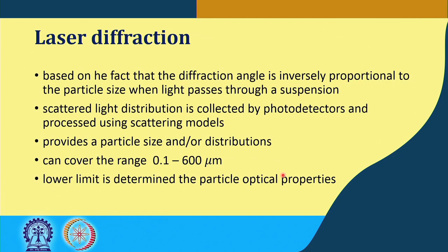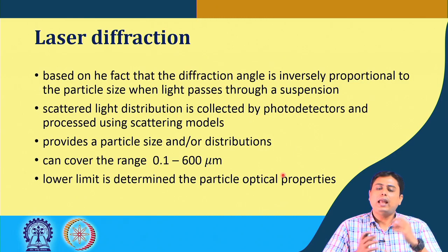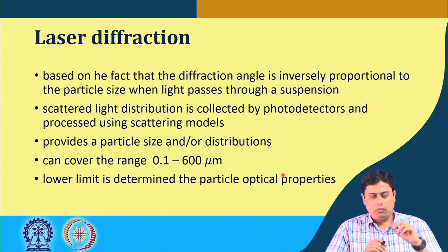The last methodology is the laser diffraction. In laser diffraction, we calculate the sizes based on the fact that the diffraction angle is inversely proportional to the particle size when the light passes through a suspension. So, if you have some particles suspended in a fluid media, you throw a laser light, and the light will be scattered when it is incident on a particular particle.